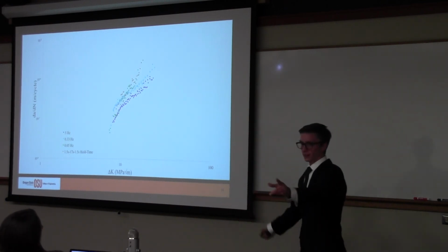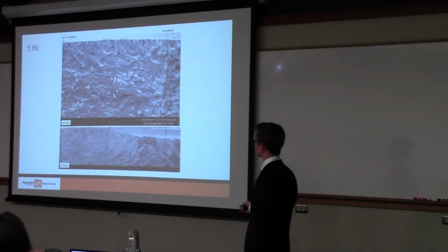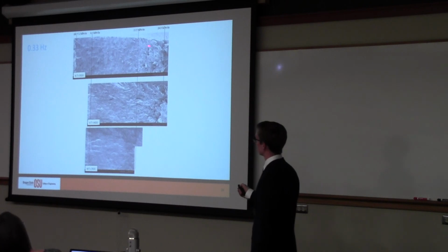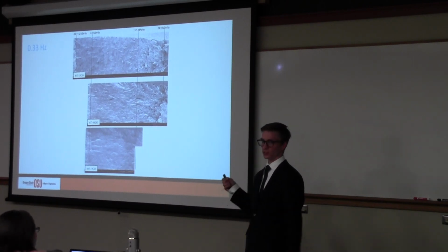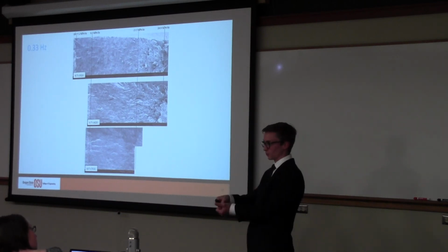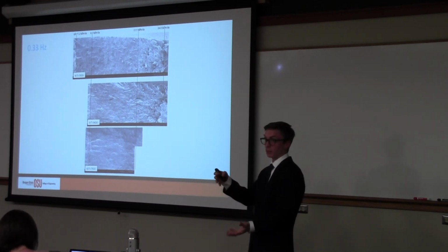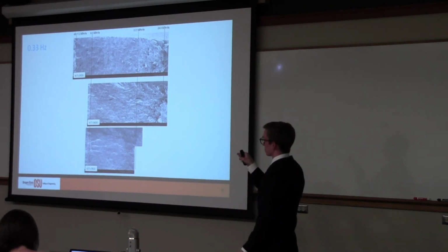Right, okay. So the roughness that we see on the fracture surfaces tells a story about a time-dependent mechanism that really wants to happen, but the crack is growing so fast that it can't. The crack is growing through the creep zone and the plastic zone, and they get bigger as the sample gets broken more.